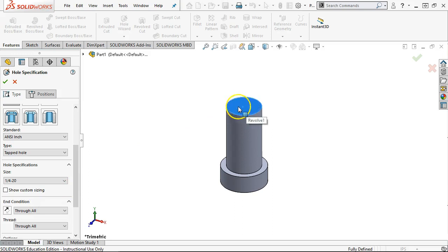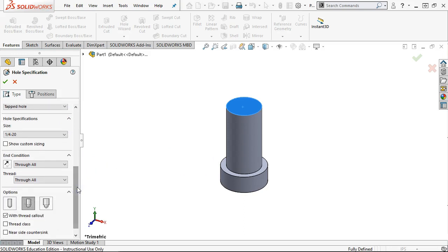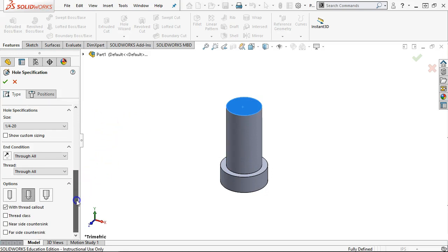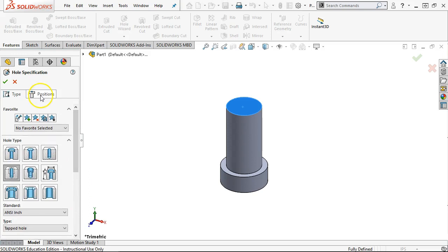So pretty much going to only leave a 1/16 of an inch on each side, but because of the load and the kind of things that I'm anticipating, I'm probably not going to make this out of aluminum. This is going to be a stainless steel part or a steel part, and that way we can have a decent finish and be able to if it does spin, if the inner housing of the bearing does spin on this, it will have some wear resistance.